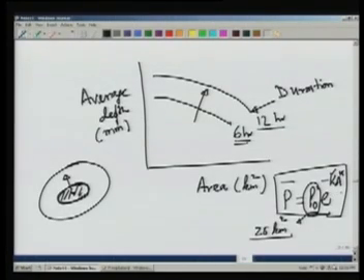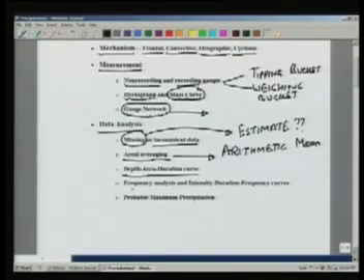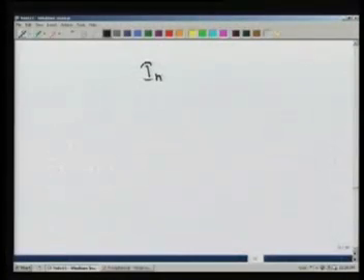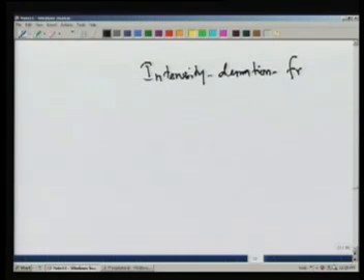and some typical values are given in various textbooks about different areas. The other aspect which is important is to have some kind of frequency analysis or risk analysis to see what are the chances of rainfall occurring in the next 10 years or next 100 years or so. So the frequency analysis is also very important from this point of view. So frequency analysis is nothing but deciding how frequent a rainfall would be, and typically what we do is present an intensity, duration, frequency curve in which we say how frequent will be rainfalls of certain intensity and a certain duration.